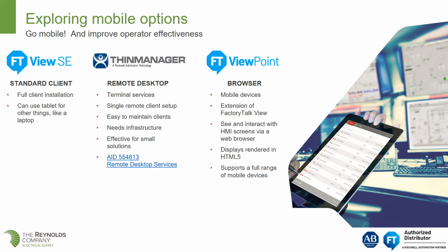All those Windows updates are handled on the HMI server. In that case, we would think about using Thin Manager, which is a layer that manages the thin clients and gets the right content to the thin clients. So we could use a thin client architecture for mobile applications.